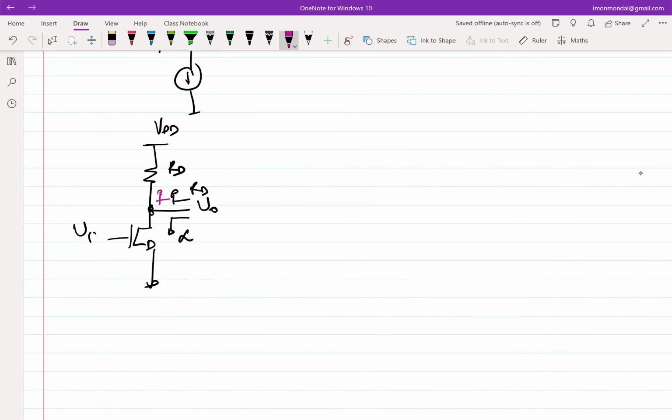And also I don't have to get infinite supply voltage to get the gain, because it's a parasitic resistance, right? It's an incremental resistance I'm looking for. I'm not looking for an exact resistance. Because the incremental current will still be GM times VI.